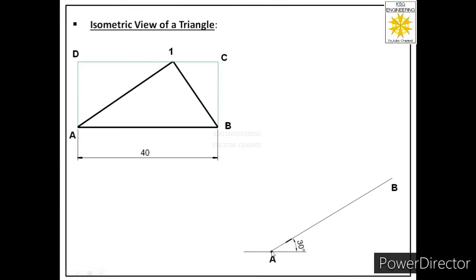Now after this, we will again put the protractor at this point and draw the second isometric axis, which will represent the width of that rectangle. So put your protractor at this point and draw the second isometric axis of any length at the start, at 30 degrees to the horizontal. Then we have to measure the width of this rectangle. For that we use a compass.